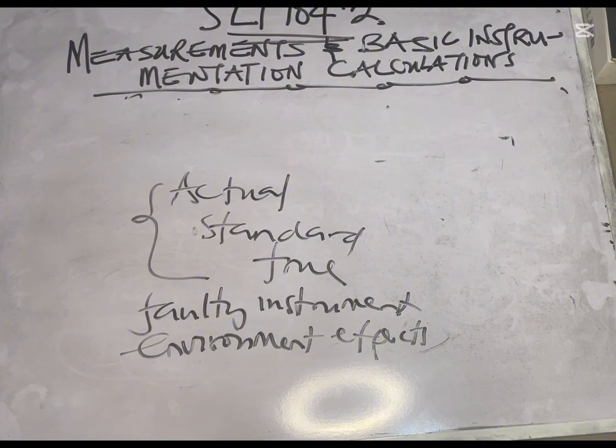You can go to the lab and see an instrument that is faulty, and you know that, no way, if I use this instrument, there's a likelihood for me to obtain wrong measured values, thereby leading to error. The second one is what we call the random errors. Random errors are unpredictable errors that occur due to noise, operator inconsistency, or unpredictable environment.